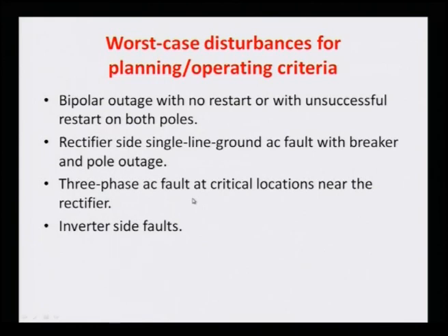Now, we saw all the modeling, and modeling includes each and every component. I said including your AC system, that is including the synchronous machine, excitation system, governor system. Then we have to go for the load modeling, and finally we have to include your HVDC system. If you have some other controllers like static VAR compensators or TCSCs or UPFC, I can say if you have flexible AC transmission system device controllers, those controllers should also be modeled and then added. So, all the controllers along with the machines should be included, and then you have to write the governing equations, and those governing equations are the differential equations along with the network equations,